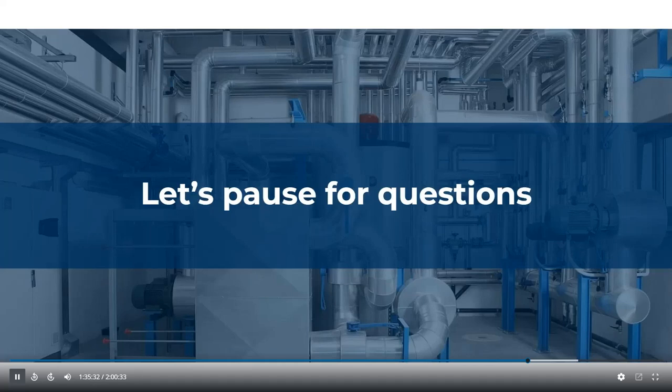Yeah, and absolutely. There's also a comment here that for multifamily housing in many sites, we're required to provide MERV 13 filtered air supply to each unit. Okay, so MERV rating 13 for that specific filter. Filters, as far as the MERV rating is concerned, that is application specific.